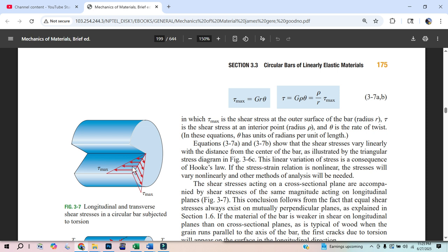The reason you have arrows going two different directions is because shear has to have those 4 forces. We said that if I have a little chunk of material, I pull down and push up, it would just spin in this direction. So I need to push that way and push that way. But if you are pushing the material that way and that way, then the surfaces above and below are shearing past each other. And so those two surfaces can rip apart. So they're experiencing the same thing.